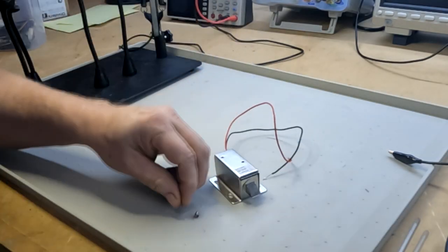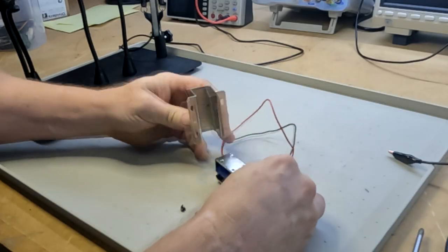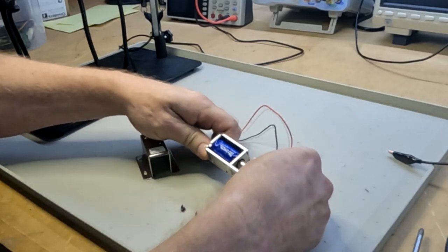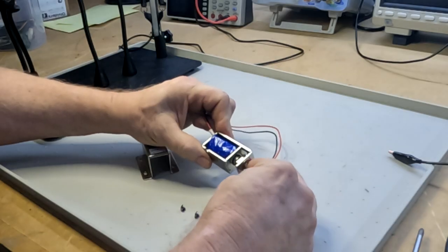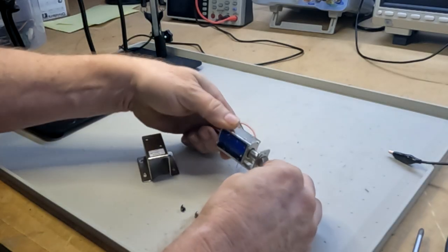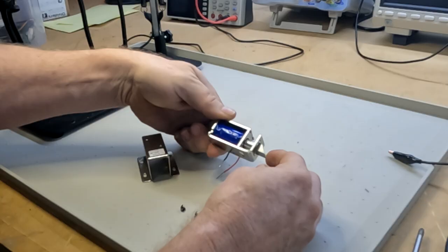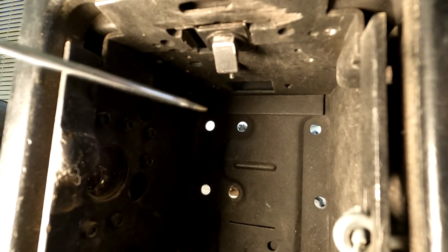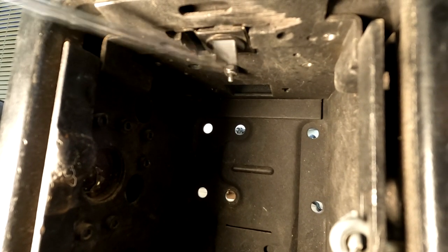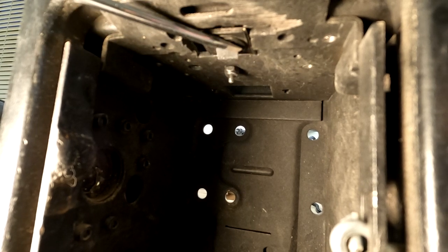You will need to place the solenoid in a vise and tap out and pry back the housing in order to remove the coil for access to the spring. Make sure everything is perfectly aligned when reassembled so that it moves smoothly. The latch is installed horizontally, so gravity will be doing the work of resetting the lock instead of the spring.